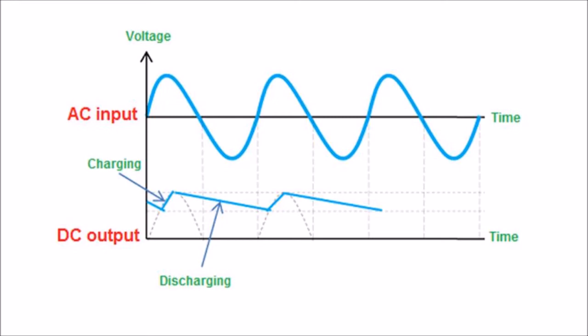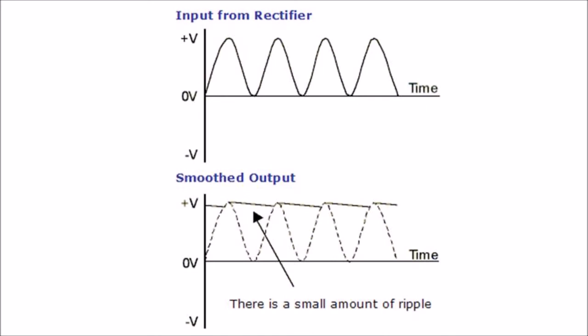During the negative half cycle, the diode D is reverse biased and there is no current in the output section. But during this negative half cycle the capacitor begins to discharge the stored charge, and this discharge flows through the load resistance RL, and thus it makes a smooth output in the load resistance RL, since a capacitor with a large discharge time constant will produce a very smooth DC voltage.